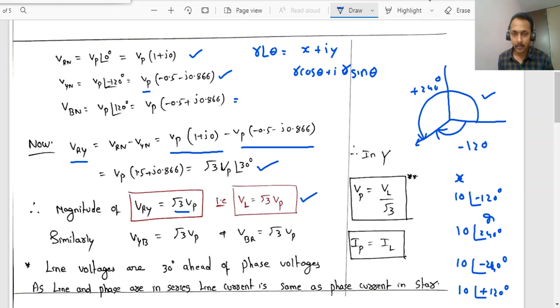It is something like, for example, if the line voltage in between two lines is 400 volts, then what will be the phase voltage? 400 by root 3. Like that we have to understand. In star connection, all this is with respect to the star. In between two lines, if the voltage is 400, then the phase voltage will be line value divided by root 3 magnitude wise. Now observe, dear students, this is very important. Angle wise, the line voltage is, observe here in this diagram.